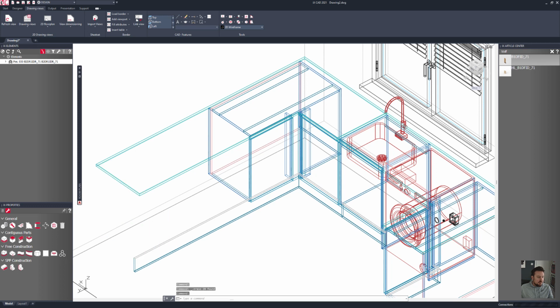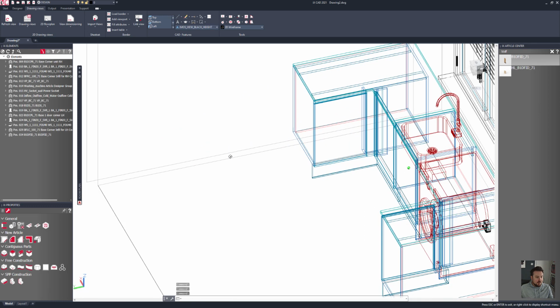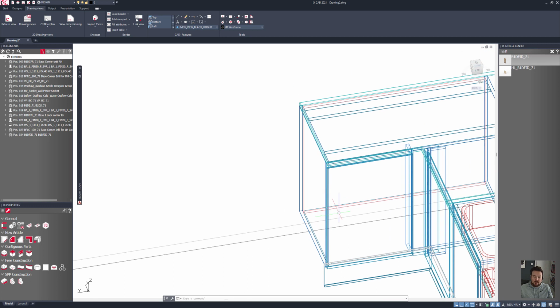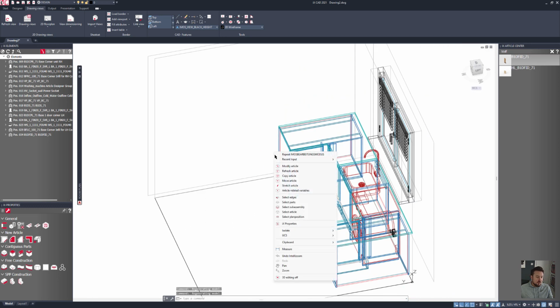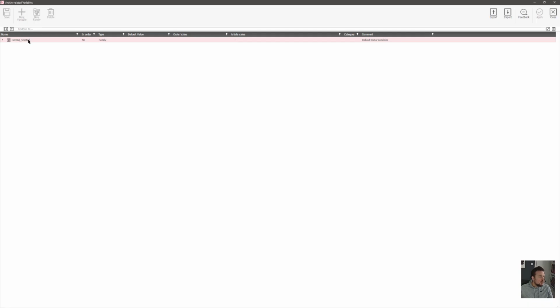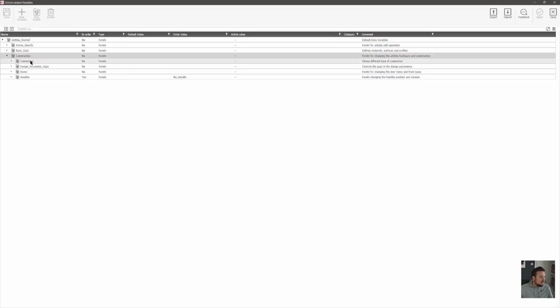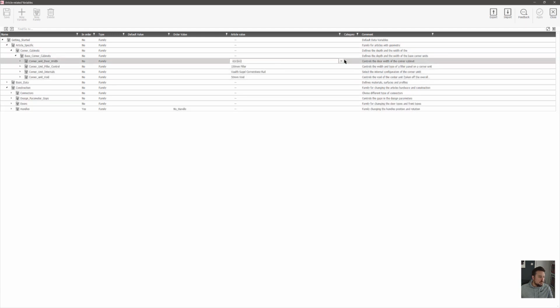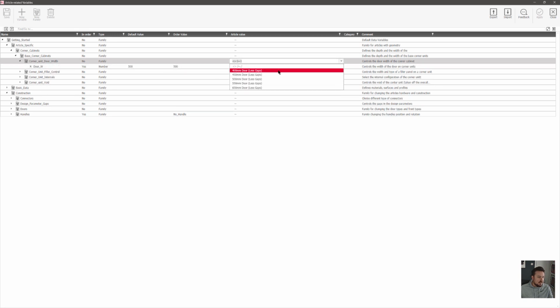I'm just going to delete it for now and add in my hob unit over on this side. Now I might need to reduce the overall width of this one just to squeeze everything in that I need over here, because I'm referring to a plan that's off the screen. So what I'm going to do is say that this should be changed, and I'll go to the article related variables for this particular product, go to the construction, and then in here under article specific you can see that I have the ability to change the door width down from the default of 500, and I'll take that down to be a 400 door, so that's going to be a lot smaller.